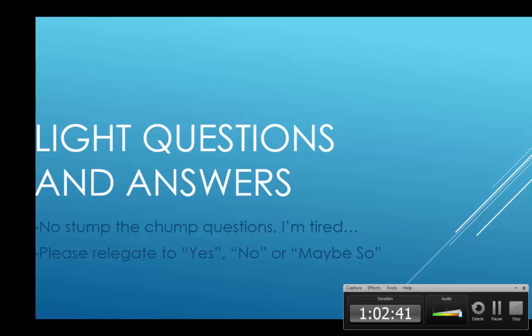Yeah, so the rules of thumb for putting part numbers in for configurations really depend on what's going on. I have seen some companies that will make a special file property for it, and they can control it through the configuration manager and stuff like that. The bill of materials actually has functionality that will allow me to simply pull the name of the configuration in, and then under the configuration properties there is a checkbox to say, hey, if I'm used, this is what I want shown. One of them is the configuration name. You can write a number in there, or you can just say use the file name, which will kind of trump anything that you were looking for. But it does need to be hand managed at that little checkbox level.